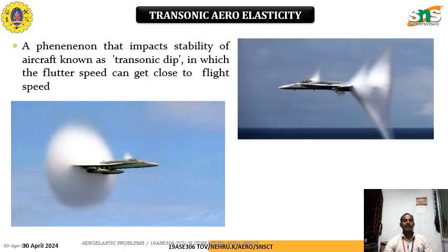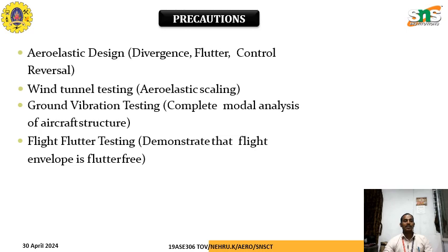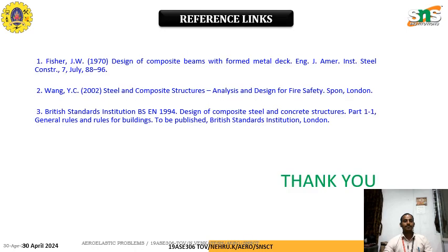In transonic aeroelasticity, the phenomenon that impacts the stability of aircraft is known as the transonic dip, in which the flutter speed can get closer to flight speed. Location, aerodynamic design, divergence, flutter, control reversal, wind tunnel testing, aerodynamic scaling, ground vibration testing, and complete model analysis of the aircraft structure can be done to reduce this flutter effect. Flight testing and flutter testing demonstrate flutter-free operation within the flight envelope.